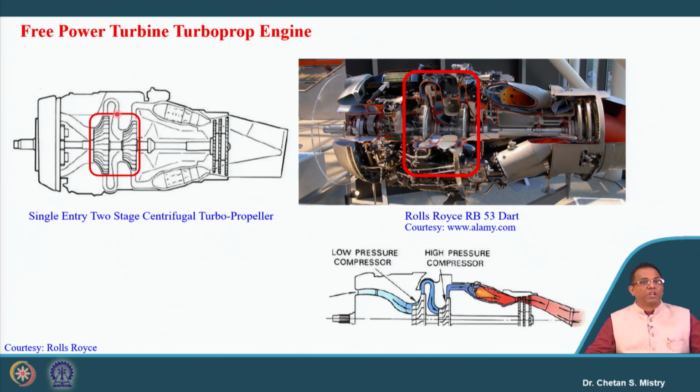Again, that's what is being passed axially. So this is the flow channel. That needs to be designed carefully, because you can imagine my flow is turning too much here and then moving inside, where there are more chances for my pressure to drop, and that will increase the losses. But when we are looking for a compact size of the engine, then we have this kind of configuration. That's what is possible.